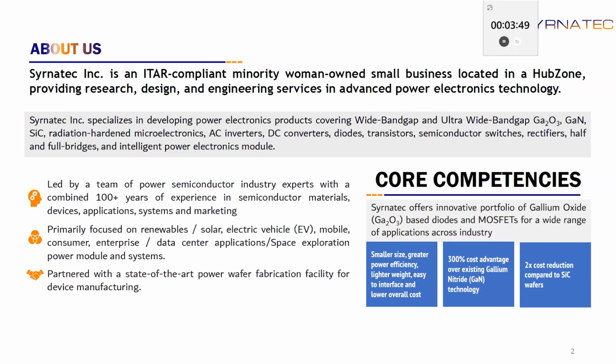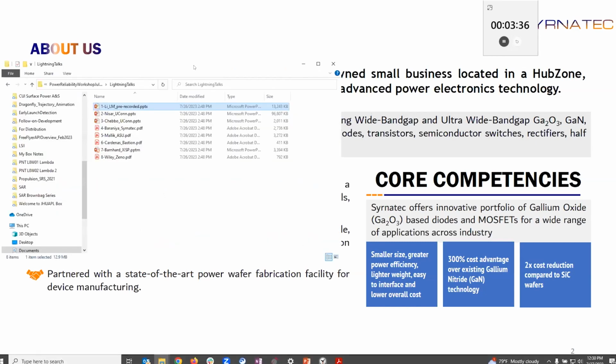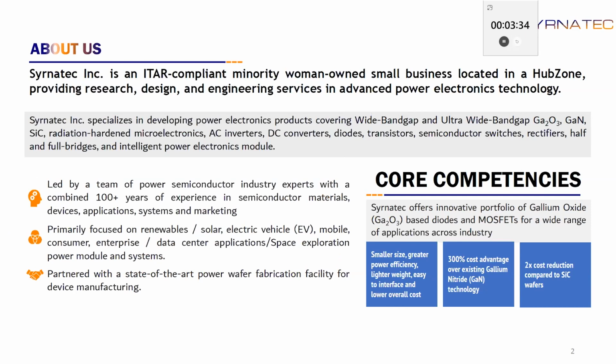that silicon carbide, while it can handle high power density, is not radiation tolerant. A lot of the transistors and other electronics that are based on silicon carbide have premature failure, single event burnout, single event effects, and other issues that don't allow it to really be used for long duration missions, especially if we're talking about cislunar and lunar surface power transmission and distribution systems.